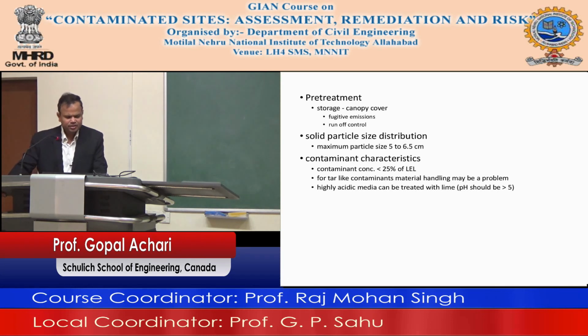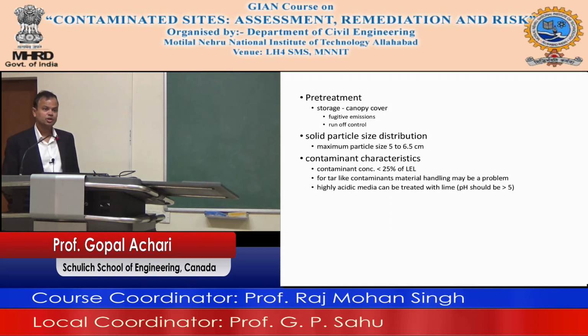The maximum particle size is 5 to 6.5 centimeters. For the contaminant characteristics, the contaminant concentration has to be less than 25% of the lower explosive limit. If you have too high a hydrocarbon concentration in there, you might have an explosion inside. You don't want that to happen.